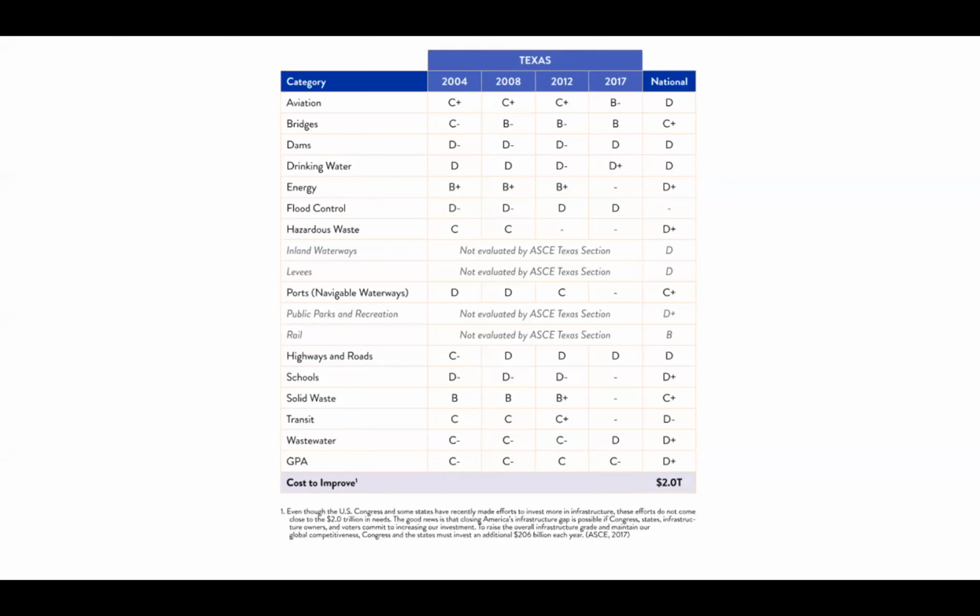What's commonly done is to use a multiplier. That is, just for sake of argument, if you had 1 square foot of concrete to be repaired, you would probably multiply that by an additional 30%, maybe 50%, maybe even 100% to account for what you can't see. And that would also account for ongoing deterioration while you're in that process getting ready to repair. So you certainly need to escalate the repair quantities. As far as hidden and undiscovered conditions beyond that, you basically have to deal with them as they arise. So a contingency for that is probably the best way to go.